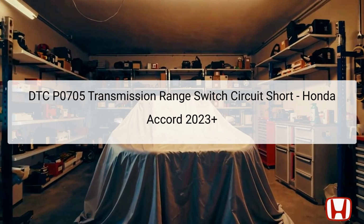The Diagnostic Trouble Code, DTC P0705, indicates an issue within the transmission range switch circuit, primarily detected by the Transmission Control Module, TCM. This code is triggered when the TCM identifies multiple signal inputs instead of receiving the correct signal for the selected gear range. The transmission range switch plays a crucial role in this system. It informs the TCM of the gear selection, impacting overall vehicle operation.